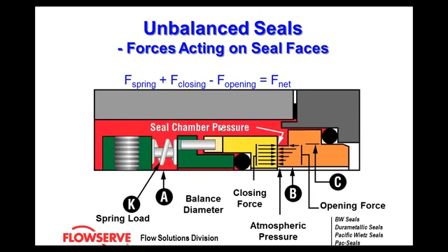The seal chamber pressure also acts to open these two faces and provide you with the lubrication needed to operate the mechanical seal. It starts out at a higher pressure in the seal chamber, and then goes to a lower pressure as it approaches the atmospheric side.